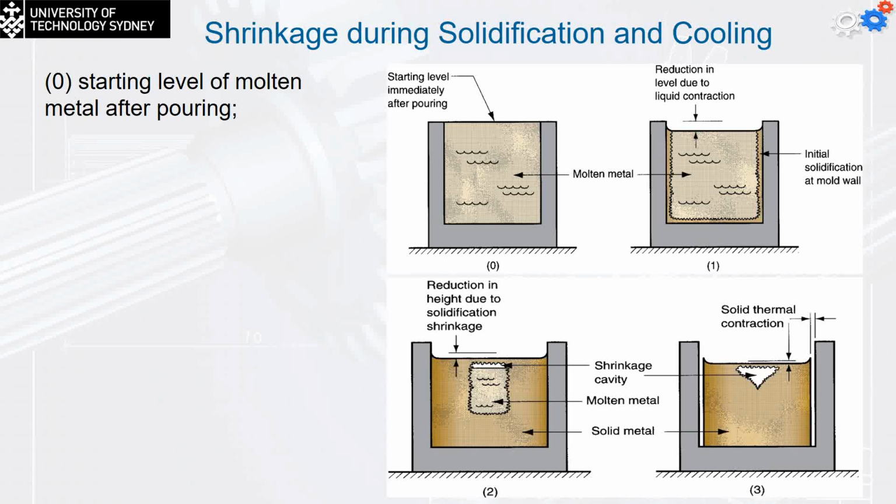With this preliminary solidification process, the size will be shrinking. But this shrinking is going to be from the top. So you can see that the level will start to drop from the top. As the solidification continues, the level will drop further. The molten metal remains in the center, where the heat diffusion rate is going to be less, and the contraction will force the part to leave the wall and shrink to the middle. And usually, if the pouring temperature and the pouring rate were bad, we are going to have a cavity in the middle, and this should be removed. This is a disadvantage.